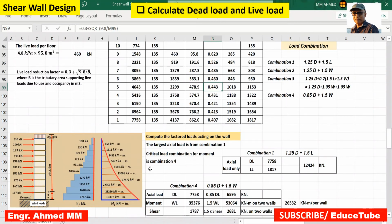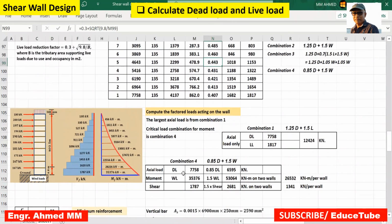The reason is the largest axial load will come from combination 1, largest axial load. So we are using this combination 1.25, this one 1.5, this one, we get this 12424 kilonewton. We got it, axial load only. When we go for combination 4, it is 0.85 dead load, 1.5 W. This is actually wind loads.